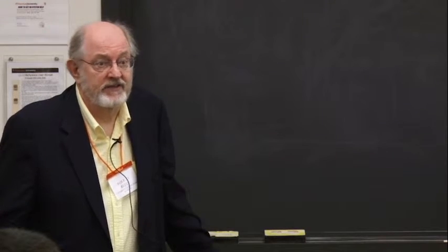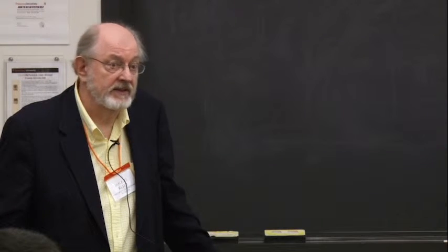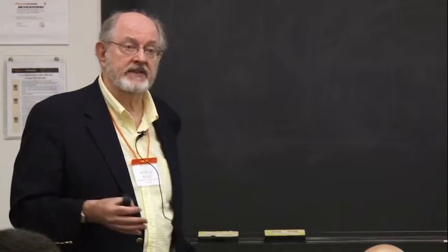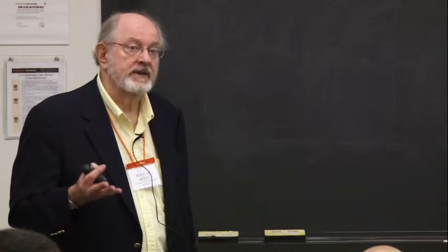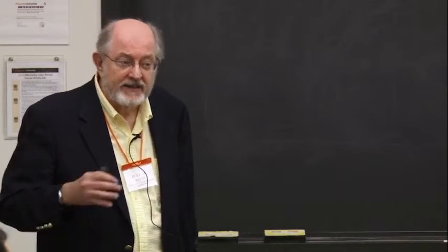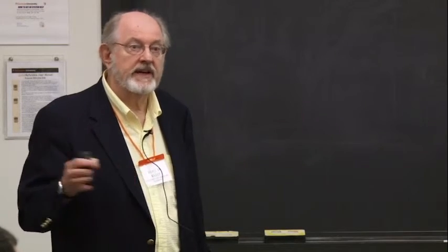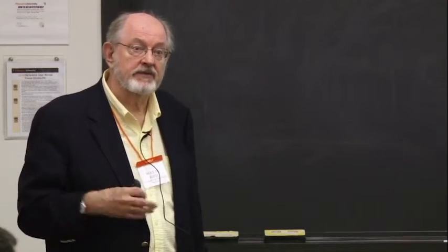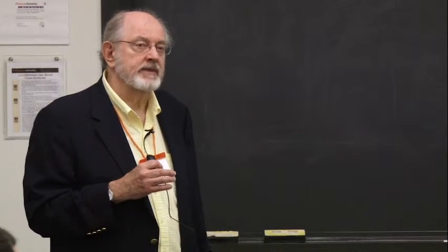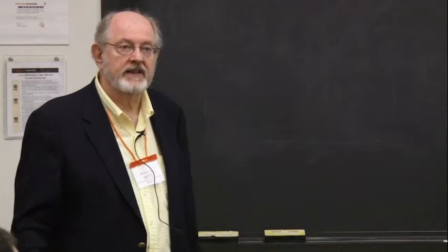You could infer it from the simulation. I don't know if I would believe it, though, because you need really high resolution in time to be able to track these waves very accurately. But that would be what would be required, right, is to look at the Mach number, somehow decompose the fact that you have various modes, not just a radial mode, but those circumferential modes. And I'm not sure that people know that much about detonation waves to be able to say how they operate in such a complex environment.